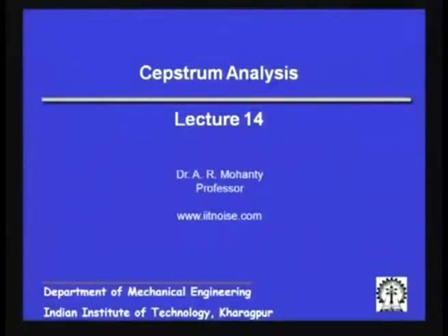In this class, we will talk about something known as Cepstrum analysis. Well, by now you know that in signals there could be sidebands because of modulation. We have just seen that sidebands could be because of frequency modulation or amplitude modulation. In the case of amplitude modulation, I have the sidebands Fc plus or minus Fm, and in the case of frequency modulation, I have Fc plus k times Fm, where there will be multiples of the modulation frequencies.